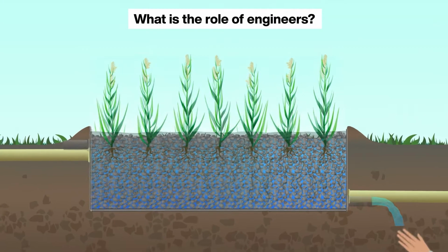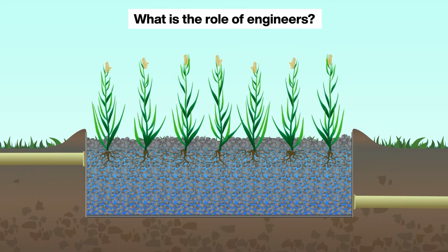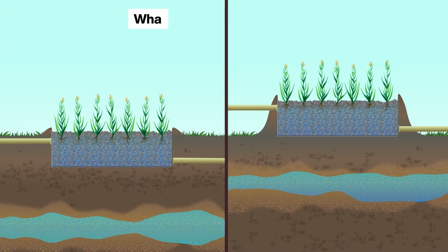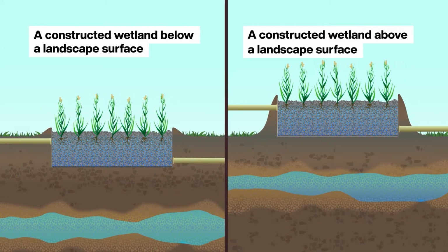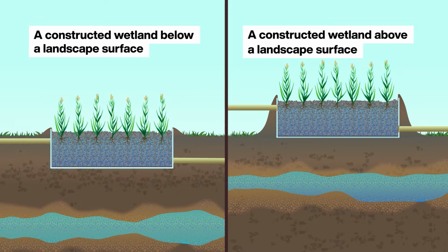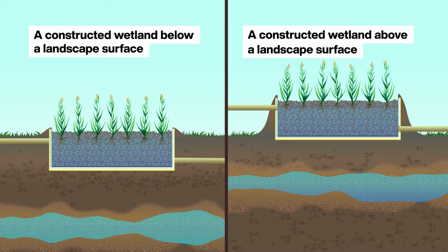If the groundwater is deep enough, a subsurface flow constructed wetland is built. If the groundwaters are shallow, the wetland bed is constructed above the surface. Then engineers choose the materials and build the skeleton equipped with hydro insulation and thermal insulation if necessary.